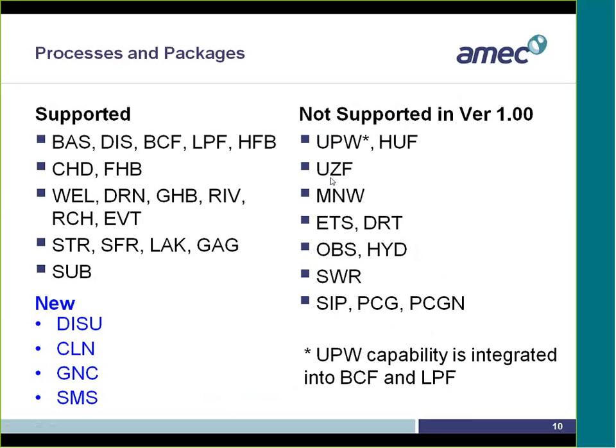And on the other side, these are not supported. The solver packages are not supported because the original MODFLOW solvers are structured and they cannot be used with an unstructured grid. But otherwise, the other packages are currently not supported and they may be supported in future versions. For instance, the ETS and DRT packages have been useful. The MNW package is useful.